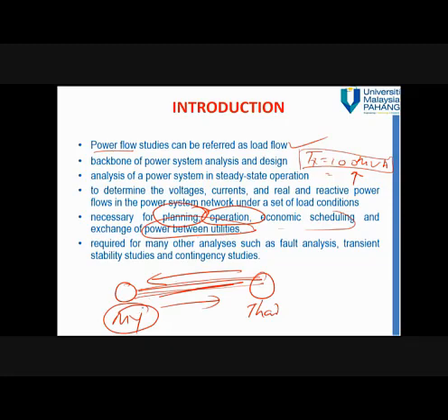We have to know how much power is needed by Malaysia during the day and how much power is needed by the Thailand utilities during the night. Usually power flow is required by many other analyses such as fault analysis. That's why I said before we run the analysis, we have to run the power flow, usually to make sure that our model in any software is right.